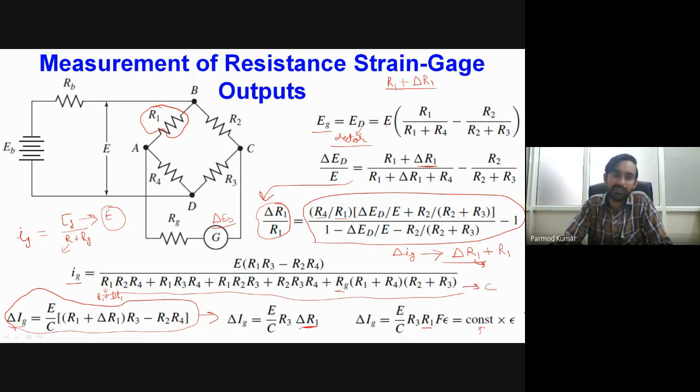Majority of the time, the current signal from commercially available transducers is in the range of 4 to 20 milliampere, and similarly there are certain transducers designed for voltage output, with that voltage in the order of millivolts.